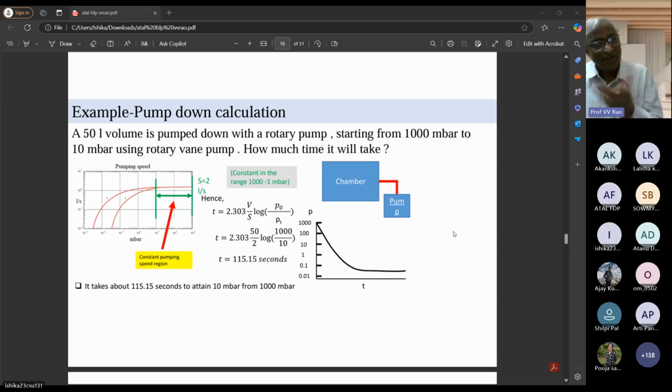So if it is coming, then the pump is running, and you can put your hand slowly and just see whether it is running. These are the tricks. Okay, and you should check whether it is getting very hot or not. Then unnecessarily it is compressing a leaky gas. That means in your chamber, some door is open. That may be a reason.